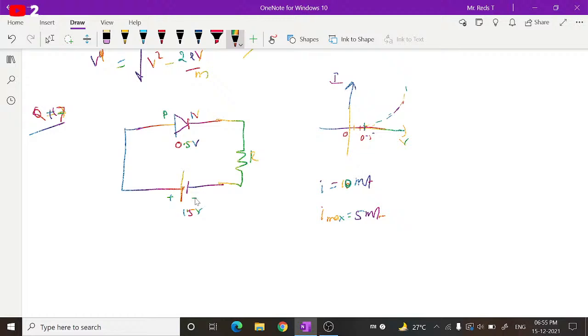1 volt. So the resistance from Ohm's law: V is equal to IR, and hence R is equal to V by I. Delta V, the potential difference, is contributing the current in the circuit, so R is equal to delta V by I. To get the maximum current of 5 milliamperes on connecting to a 1.5 volt battery, 1.5 minus 0.5 volts will be acting over there.